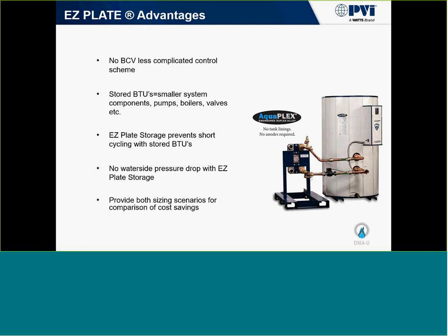So it's a basic system. It operates the same as the COBREX with a T-stat and a pump. It's just a different heat source. Instead of using steam with a steam heat exchanger, we're using boiler water with a boiler water heat exchanger.